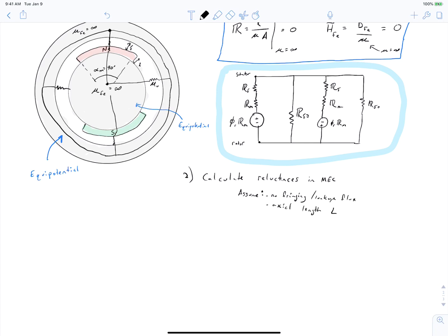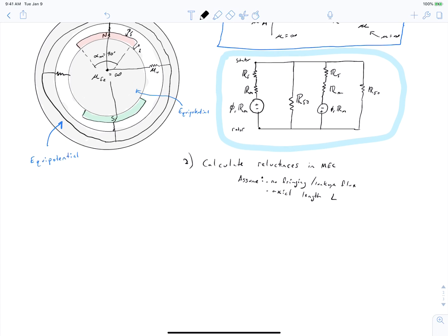And we're going to do this in a similar fashion to how we did it in a previous video for calculating the reluctance of a magnet on a shaft. And that is, we'll break our magnet up into arcs of a differential thickness, which have the same angular span as our magnet. And as we know, the linear length of an angular span is going to be the following expression: the angular span times the radius.